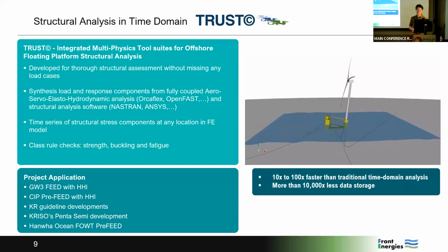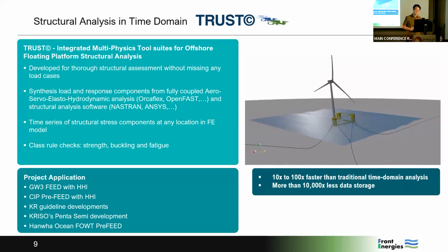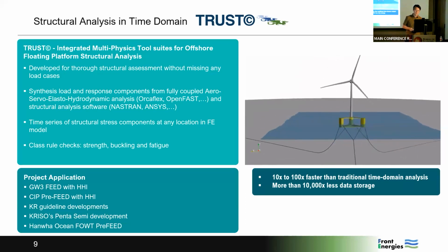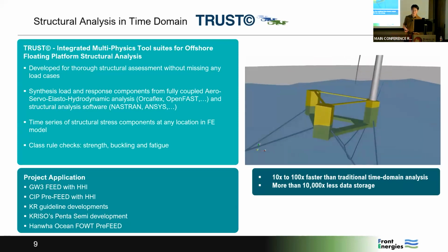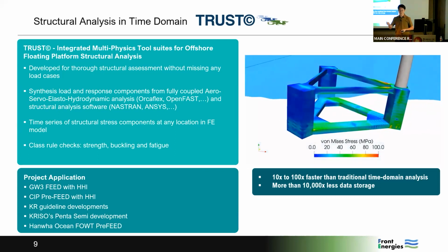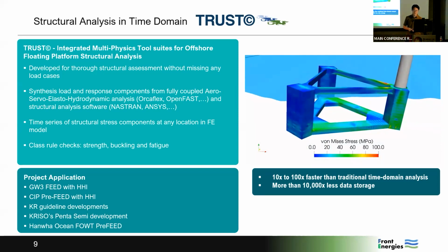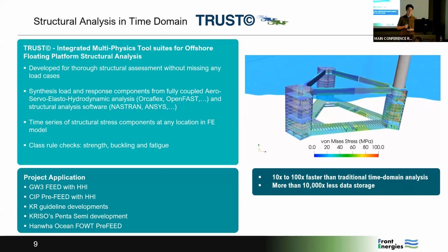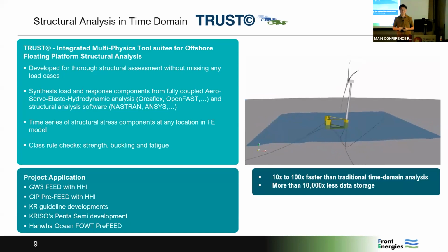The next thing is time domain structural analysis. We developed this tool. Using the finite element system and the CFD results, we can get a time series of the structural response as it is from the structural model. The main objective of developing this time domain structural analysis tool is that we don't want to miss any load cases.